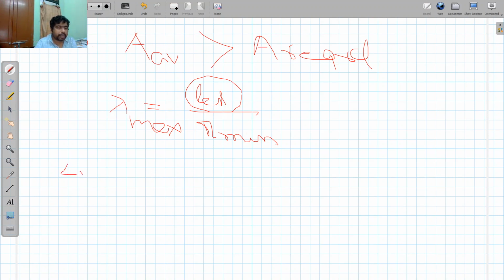Now what to do in the next step, step number 4? Once we have the lambda information, we can go to our code book, IS 800 1994, and to Table 5.1 given in the code book, and from there find the actual value of sigma sc.